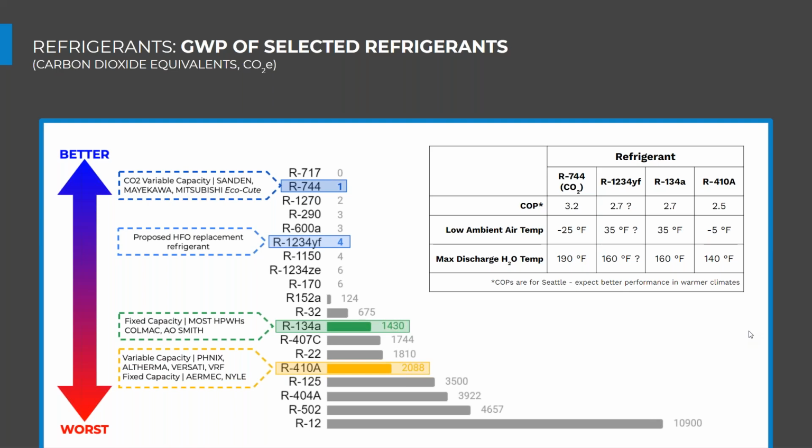Active, the refrigeration circuit is essentially turned in reverse, or there's a bypass route established. And so we're using the hot gas to melt the ice that's on the evaporator coil. Passive only works when the ambient air is above 32 degrees Fahrenheit, because we're essentially operating a fan to move air across that coil to melt the ice on it. And that's typically a much longer and slower defrost cycle than an active cycle.